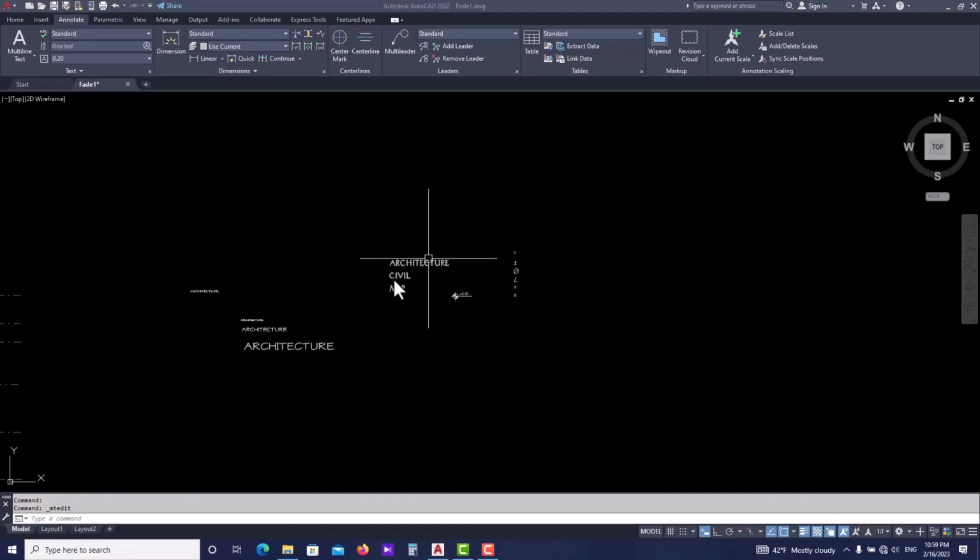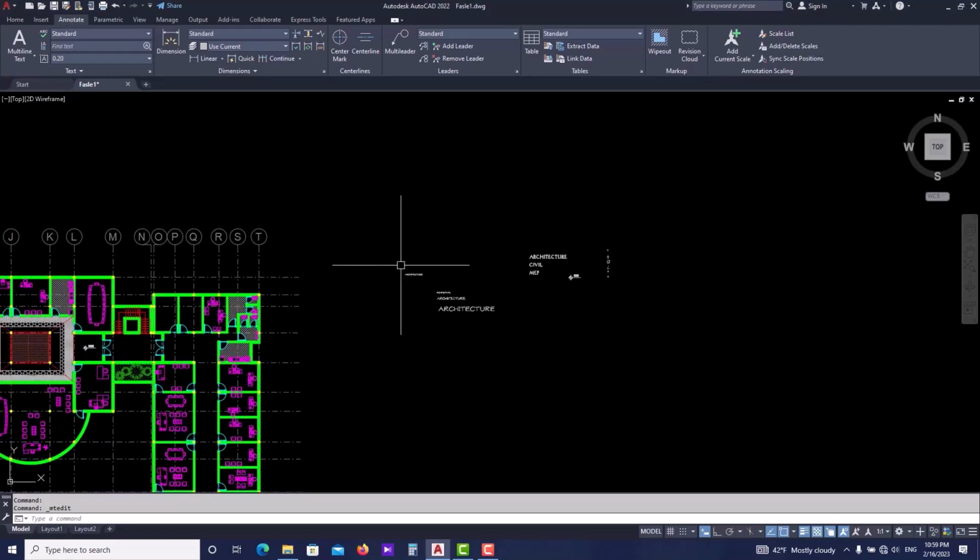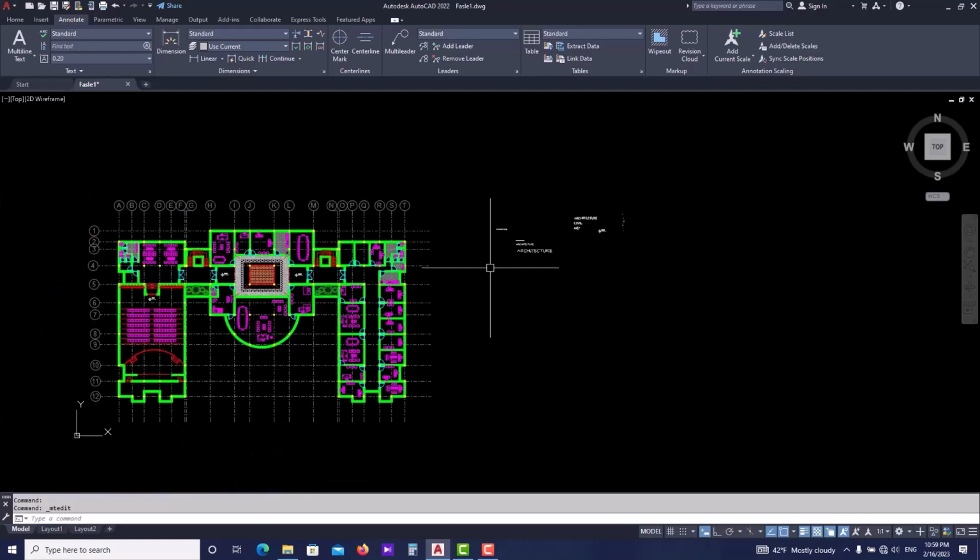Now guys, whatever we just learned here were about English fonts and English language overall. Let's see how we can use different languages in AutoCAD and how we can prevent our fonts from being disorganized. For example, let's say we want to use Persian fonts and Persian language. For that, we are going to use something called scribe fonts. Now, scribe fonts are some kind of a list of different fonts that you can download, then set in your software path. Then you can load them in AutoCAD, and then you can use them.